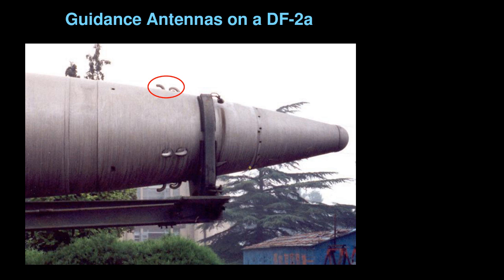to reach its target. As I said before, one of the other things that you need to do is, once your onboard computer has taken the information about where the missile is and how fast it's going, it then keeps calculating what speed and direction and altitude do I want to be able to reach my target. When it reaches that point, you would like to shut off the thrust so that at that point it heads toward the target. For liquid engines, you can shut down the propellant flow, so you can shut the engines off. It's more complicated for solid missiles, which I may be able to come to. But that needs to be done very carefully in order to control the speed and the burnout angle precisely.